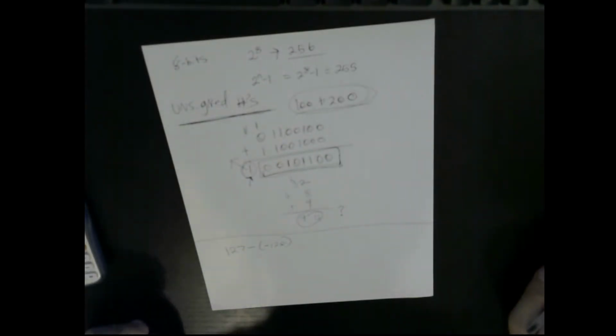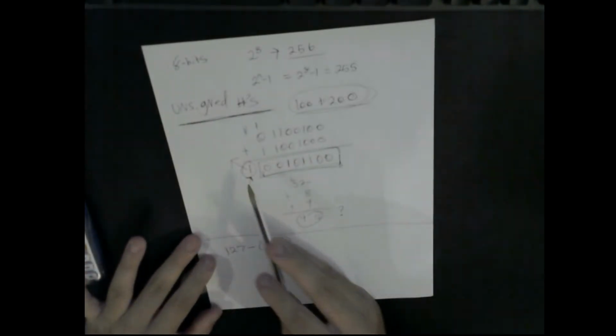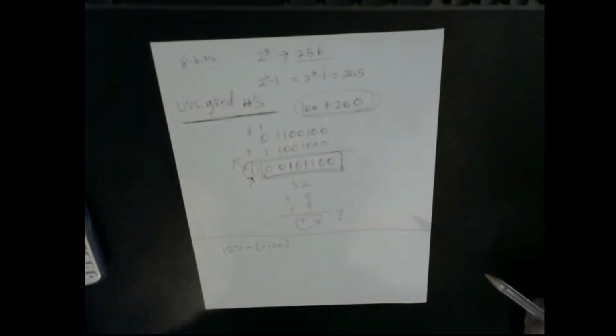So with two's complement numbers, how should we detect an overflow? Well, we don't want to look at this carry bit because the number system is a little bit different, right? Because the most significant bits typically represent signs, and if a sign overflows, it might not matter in a lot of cases. So these are the two things you want to keep in mind.